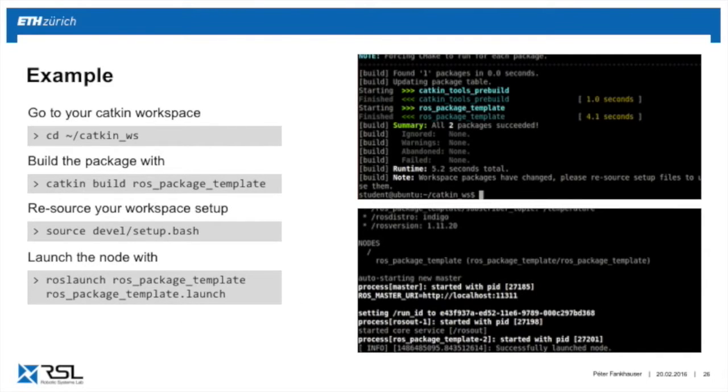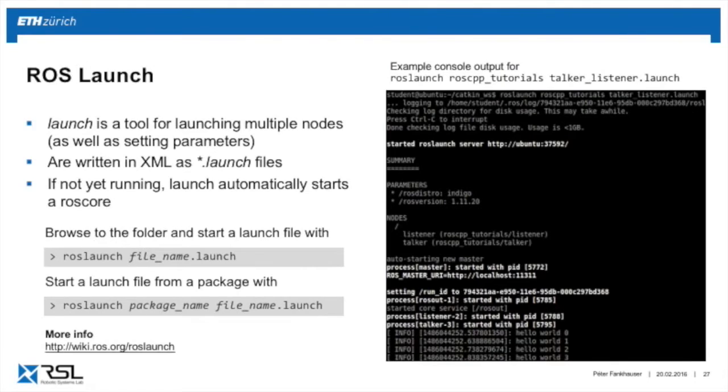Okay, so you've downloaded, built, and launched software for ROS. Now we saw in the last command that you used roslaunch. Launch is essentially a tool to run, instead of typing every time in a console rosrun, you can combine them in one launch file, which informs the system which nodes and which information does it need to load. It's a very convenient tool to run your system. These launch files, and this is important, you'll write one in the exercise, are written in an XML language and are stored in .launch files.